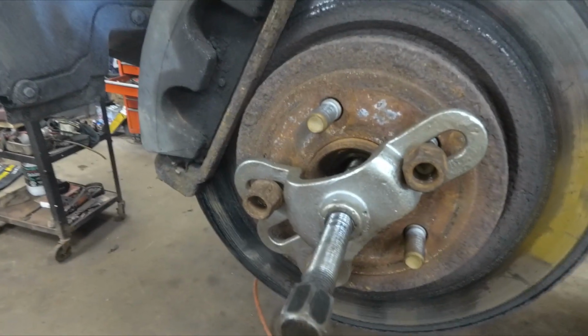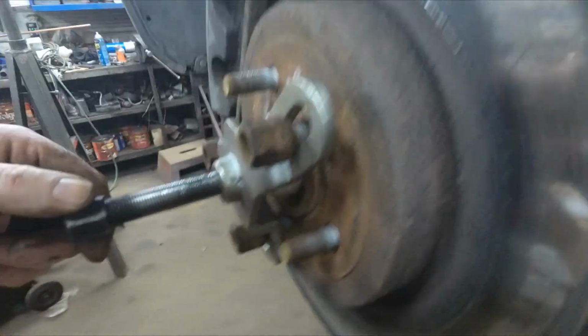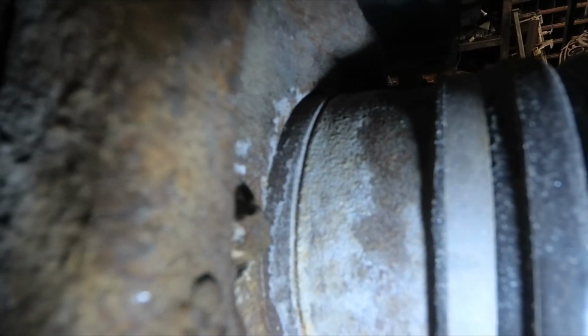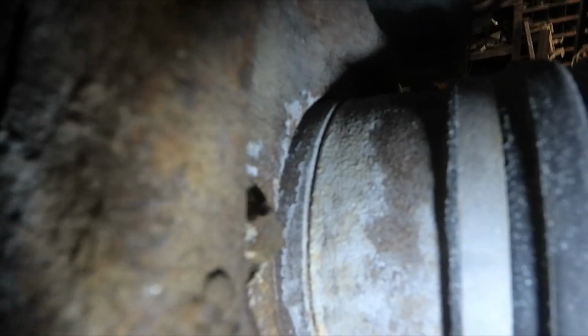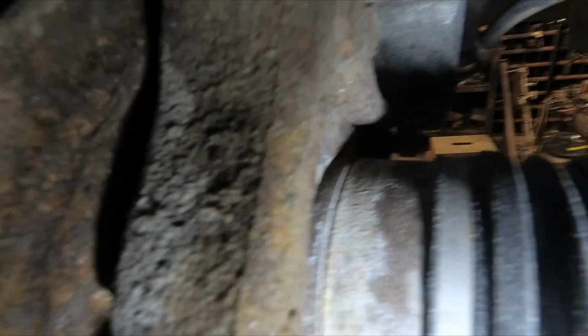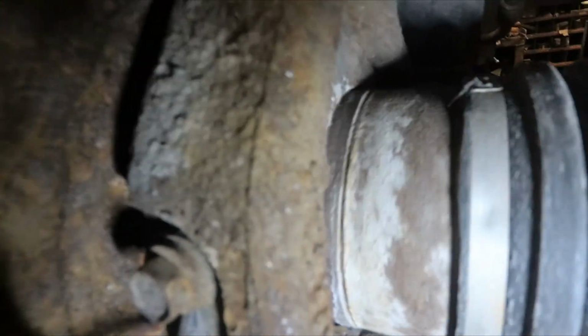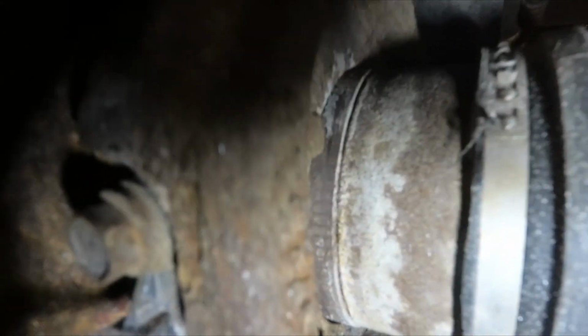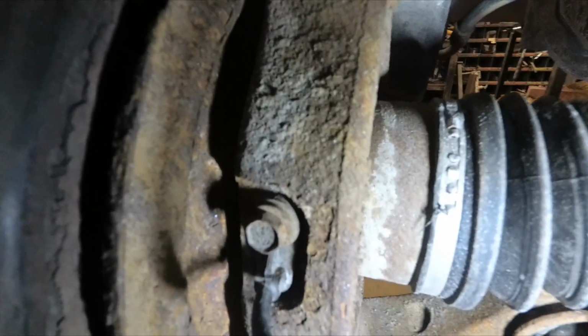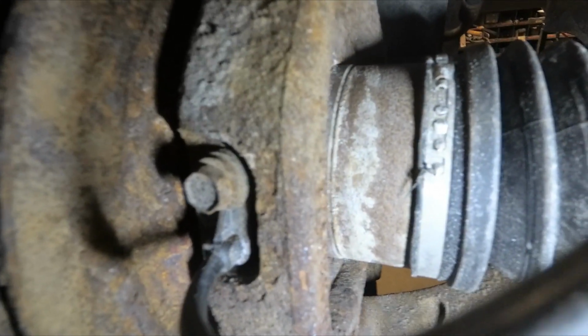So if you take the axle nut off and put a pressing tool in here, you can actually get in here and actually see the speed sensor reluctor. You push the axle shaft in, you can see it. Now this reluctor looks like it's perfectly intact. Turn the wheel. I got a little bit of pressure up against the CV shaft. So the reluctor is there. So I guess it's the wheel speed sensor that's failed. The reluctor is definitely on the end of the CV shaft.